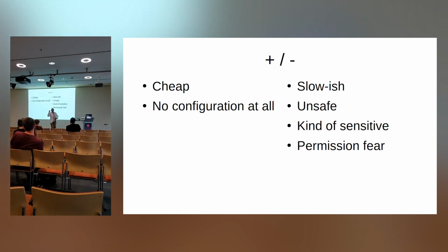Okay. This can be used for the initial setup. If you have a product which communicates via Bluetooth LE or via Wi-Fi, you can put a button on the back. The user pushes the button, and then you start to chirp out for 2 or 3 minutes the audio packages, until the application connects to the actual communication protocol. This way, you can have a one-button connect experience. The user goes, pushes the button, holds the microphone next to the device, and everything is connected. And this is very, very important because it makes the barrier to entry lower.